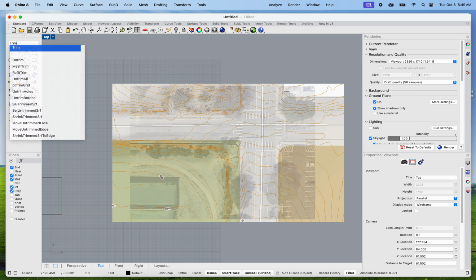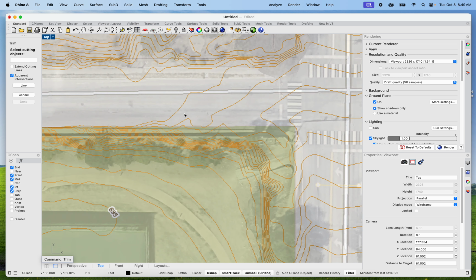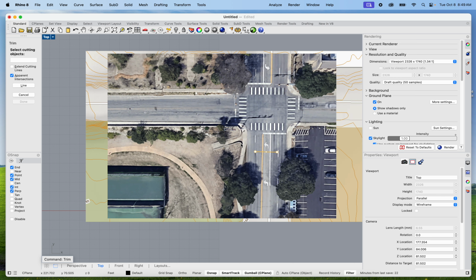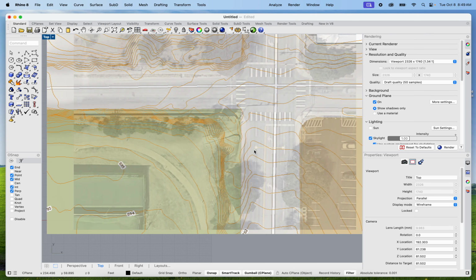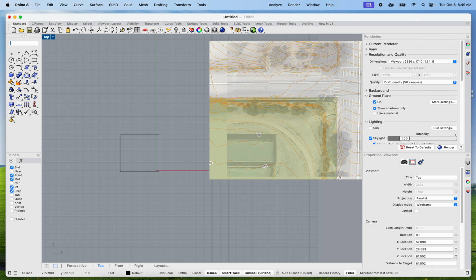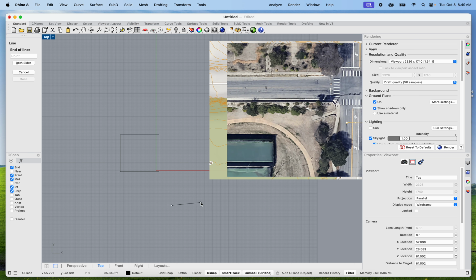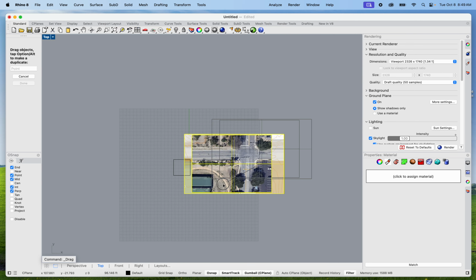However, we can trim them together, which is really nice because I really just want to talk about this section. But my measurement's over here, so I do need to make this image to scale first. I do know that my line is 30 feet and that I can draw a line at 30 feet. So I'm going to do that first. 30 feet, enter. And again, it might be a review for some of us, but absolutely brand new for some.